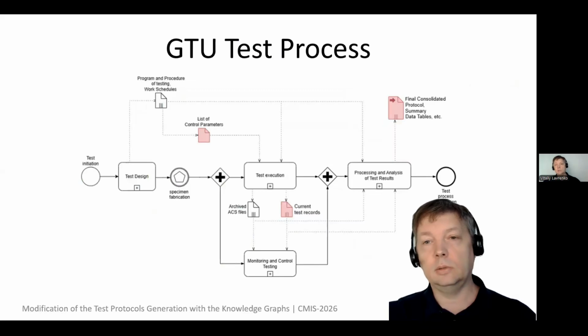Throughout the life cycle of GTUs, numerous tests are performed. During these tests, the operability of the plant as a whole and its individual components is verified. The tests are carried out in all operating modes specified by technical regulations. At the same time, critical operating parameters are continuously recorded as they reflect each specific mode.